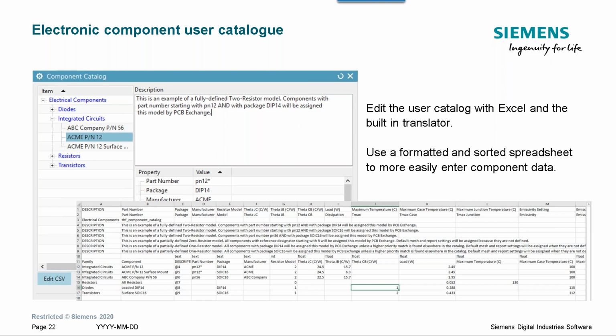But what's interesting is that the mapping can really be done based on your requirements. You can have a one-to-one mapping, so every component based on the package, based on the part number, will be mapped to a simulation object with unique properties. But also, if you want to filter some passives because they don't contribute to your simulation, or if you want to, for all specific resistor, use a single model, a single representation in your simulation, this is also possible.